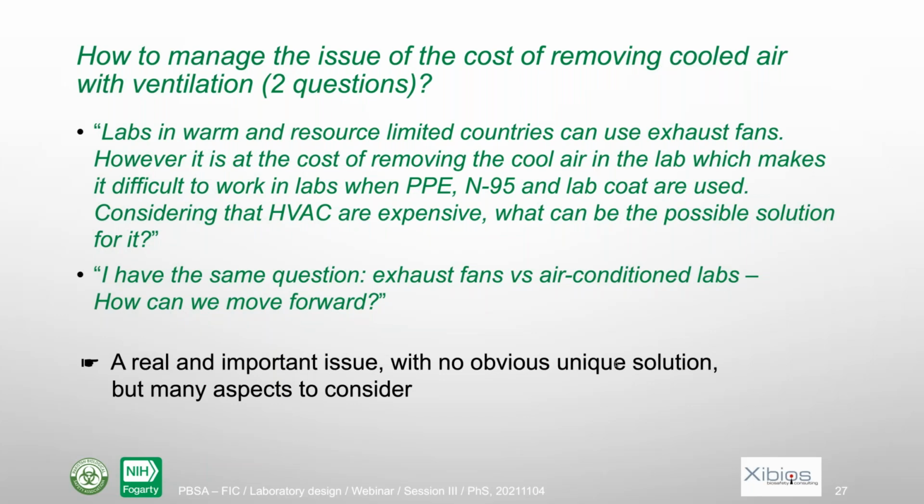The other question was also kind of opposing exhaust fans versus air-conditioned labs. But actually, with an HVAC system, the issue is exactly the same. You provide some air in one way and you extract it the other way. So you should avoid eliminating too much of that air which is cooled at high cost. Okay?